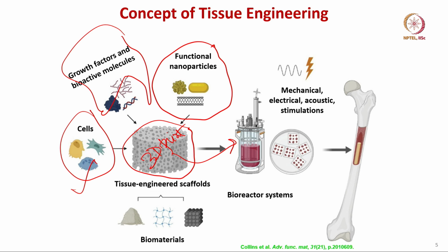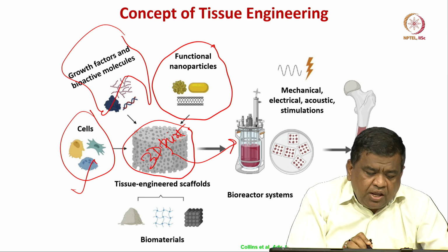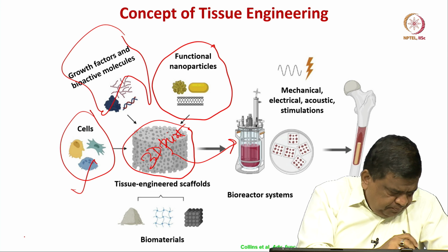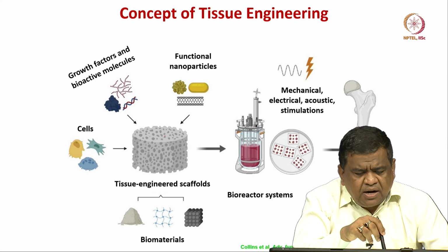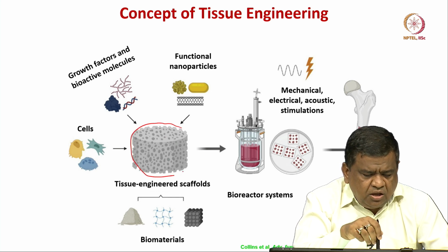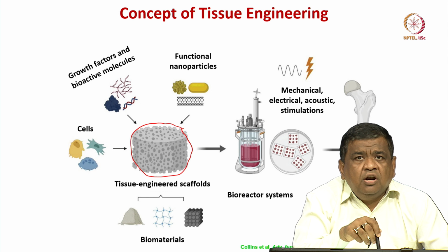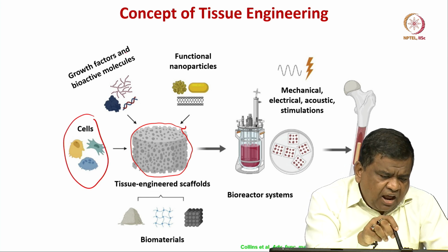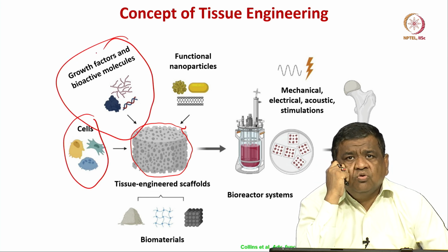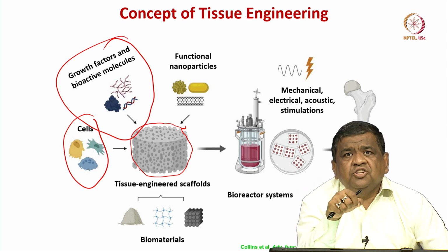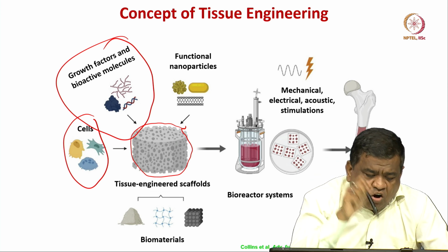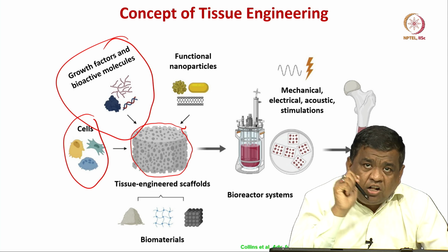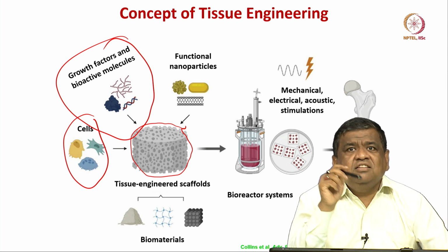Another one is that when you make the 3D print, please listen to me carefully. When you 3D print these particular structures, you do not print scaffolds only. You allow the cells and other bioactive growth factors and bioactive molecules to be added into the scaffolding gel or hydrogel or viscoelastic gel. Then you do a layer by layer fabrication process to make this structure, so that you not only get this kind of designed porous structure, but also you get the structure which contains this kind of cells,